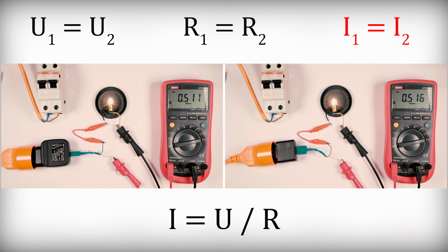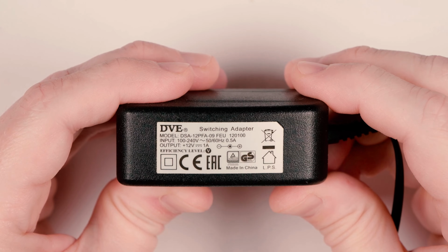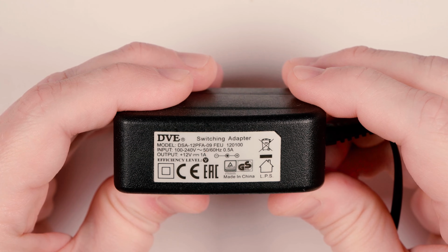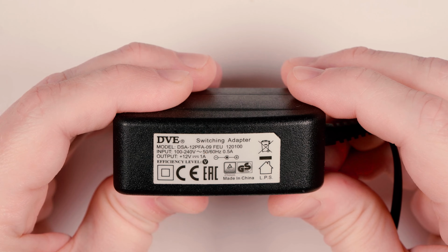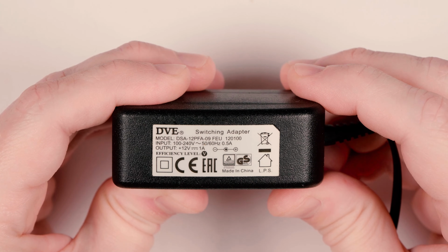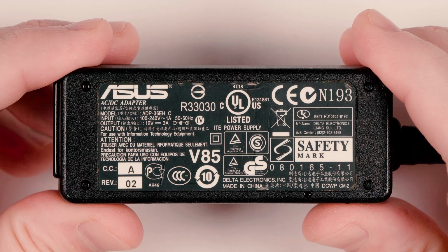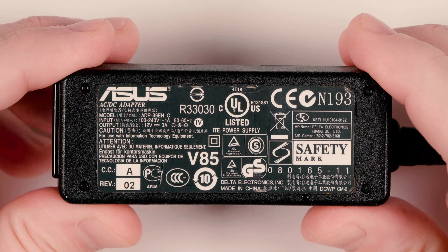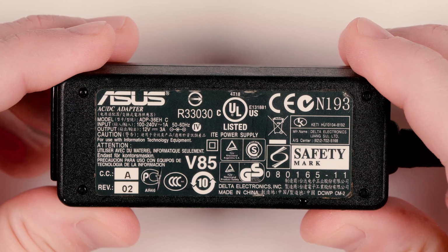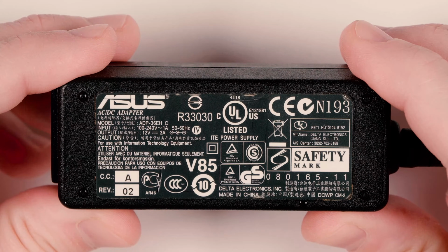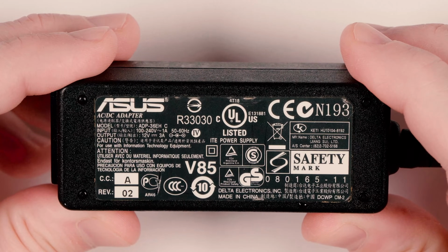So, whenever choosing a power supply, a charger for a phone or tablet, provided that the voltage is the same, feel free to choose a unit with a higher amperage. Do not believe the stories that the charger with a higher current rating will damage the battery faster. This assertion is baseless.